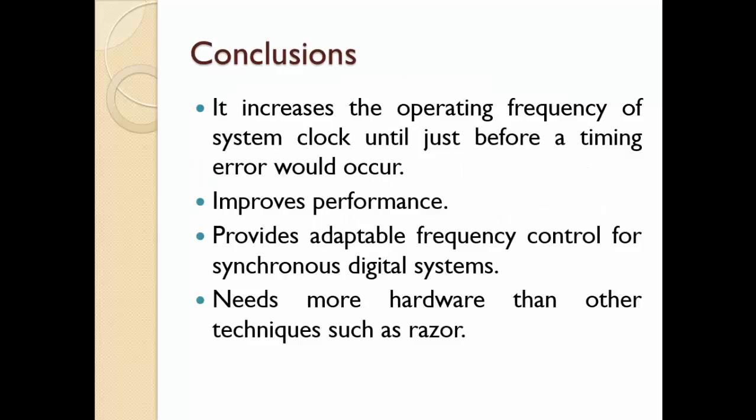Conclusion: it increases the operating frequency of the system clock until just before a timing error would occur. Improves performance. Provides adaptable frequency control for synchronous digital systems. Needs more hardware than other techniques such as Razor.